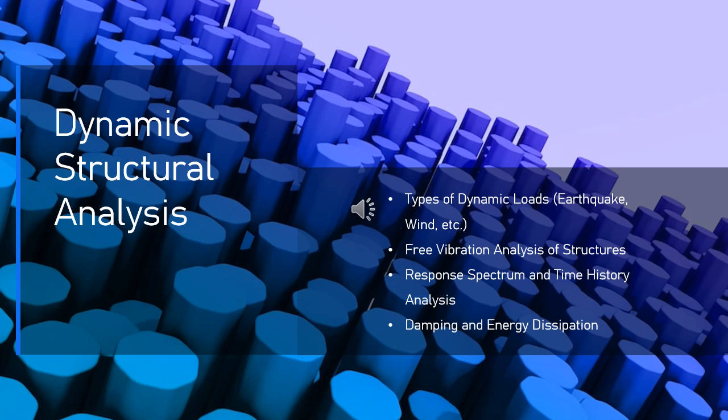Seismic design. Time history analysis is commonly used in earthquake engineering to study the response of structures under specific earthquake ground motions. This method is particularly useful when dealing with complex structures or nonlinear behaviors, such as soil-structure interaction, dynamic amplification, and resonance. Wind-induced vibrations.